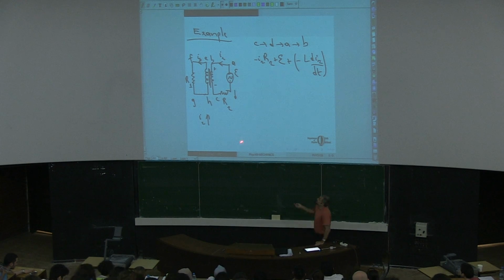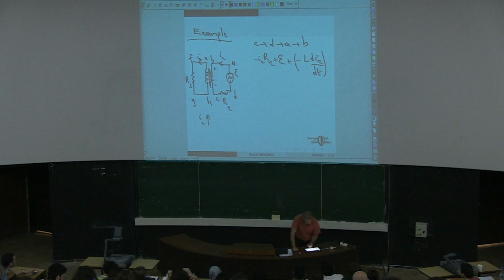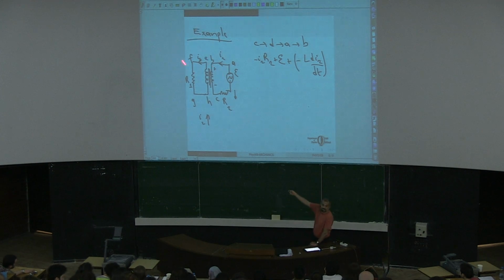This was all of it if this was just an ordinary inductor. Now the problem is this is not an ordinary inductor. There are two coupled inductors over there, so we have this mutual inductance. Even if I2 was just constant and I1 was changing, this would create some EMF in this inductor, only because of the mutual inductance between the two.